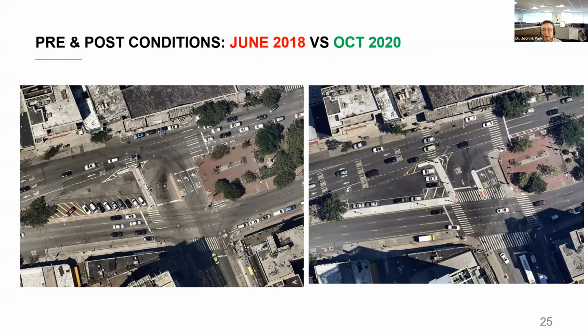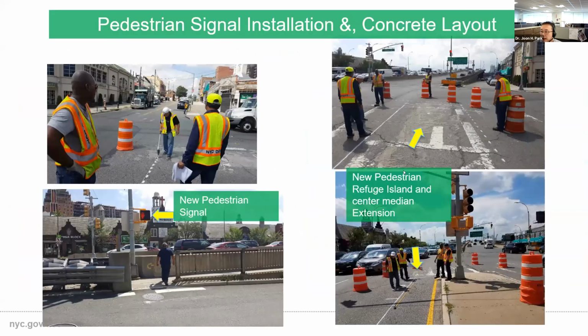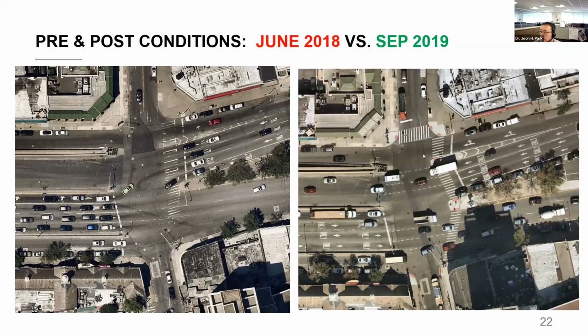Yeah, that is just as I mentioned to you. This is how we think about it, a really great question. We think about that kind of issue. That's why New York City DOT provides accessible pedestrian signals. They can hear the voice and the sound. Also, we make the pathway at least a certain number of feet wide to create some space for them. That's why we have this refuge island, even though very minimized, where they can stay, or the center median. So it's not recommended to cross a long distance in one shot. It's almost typical, even for adults or young men. So if you have a big intersection, you can divide it into several small intersections. I think that is one of the options.